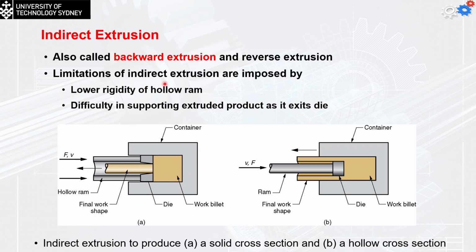It has some limitations, imposed first by the low rigidity of the hollow ram, and also the difficulty in supporting the extruded product as it exits the die in the opposite direction.